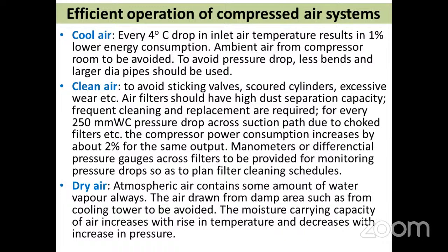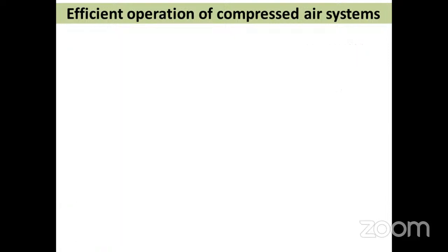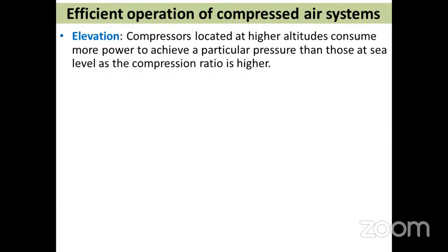The air to be compressed should be free from moisture. These are all basic requirements, sir. Elevations: the same compressor used at mean sea level will work more efficiently than one at higher elevations. This is because at higher elevations, the pressure is very low.